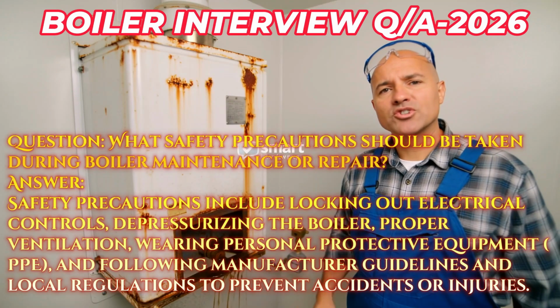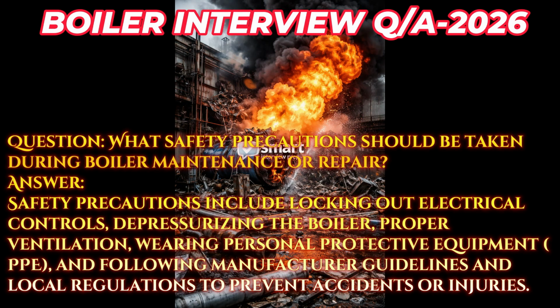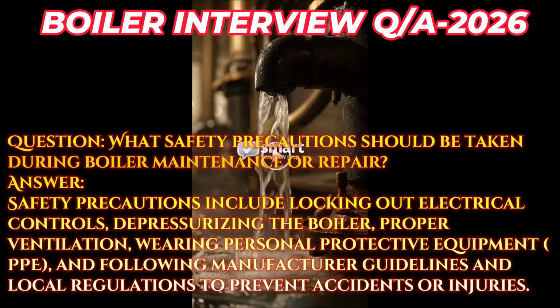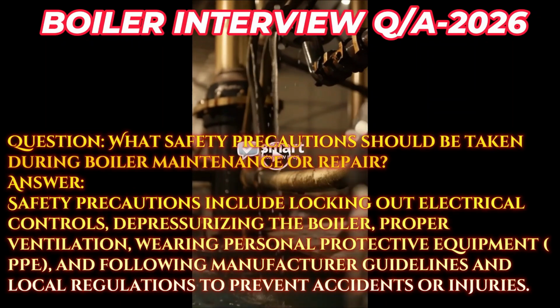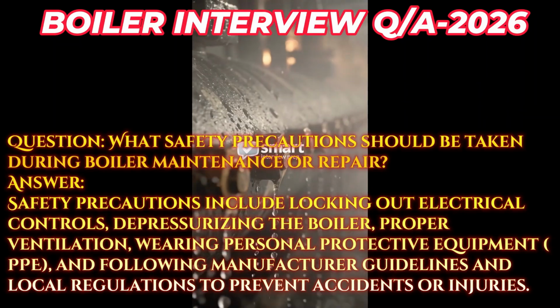Question. What safety precautions should be taken during boiler maintenance or repair? Answer. Safety precautions include locking out electrical controls, depressurizing the boiler, proper ventilation, wearing personal protective equipment, PPE, and following manufacturer guidelines and local regulations to prevent accidents or injuries.